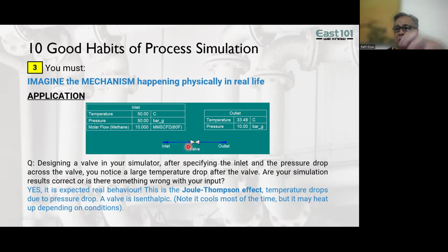So when you're expanding the gas, the attractive force trying to fight against the expansion of the gas may result in small areas where the energy of your fluid might fluctuate. You might not get an overall bulk effect, but you might get small areas where you do have energy changes, which are not captured by your standard equilibrium model, and that can manifest itself as a temperature drop.